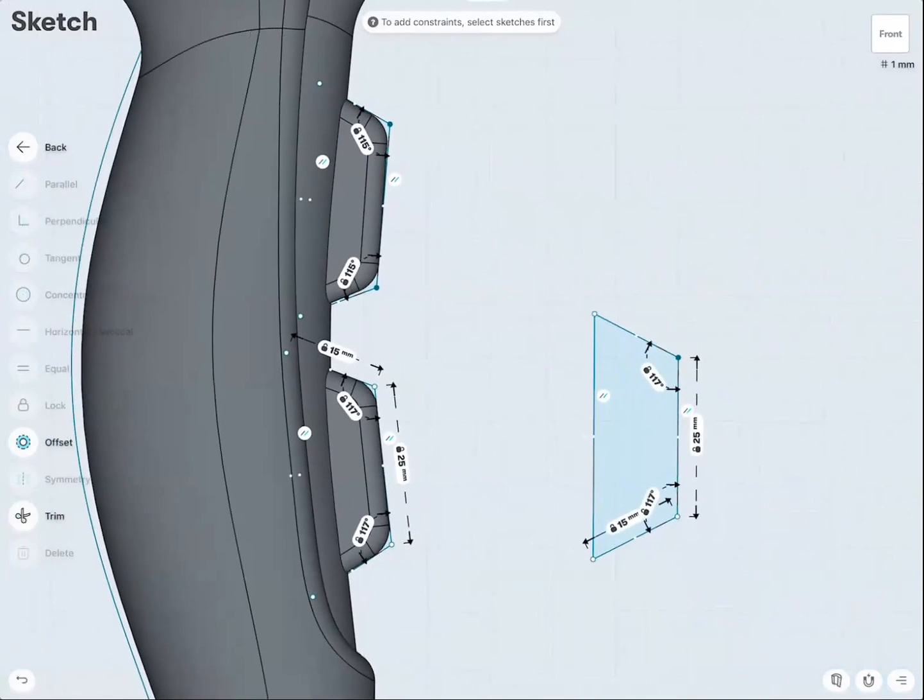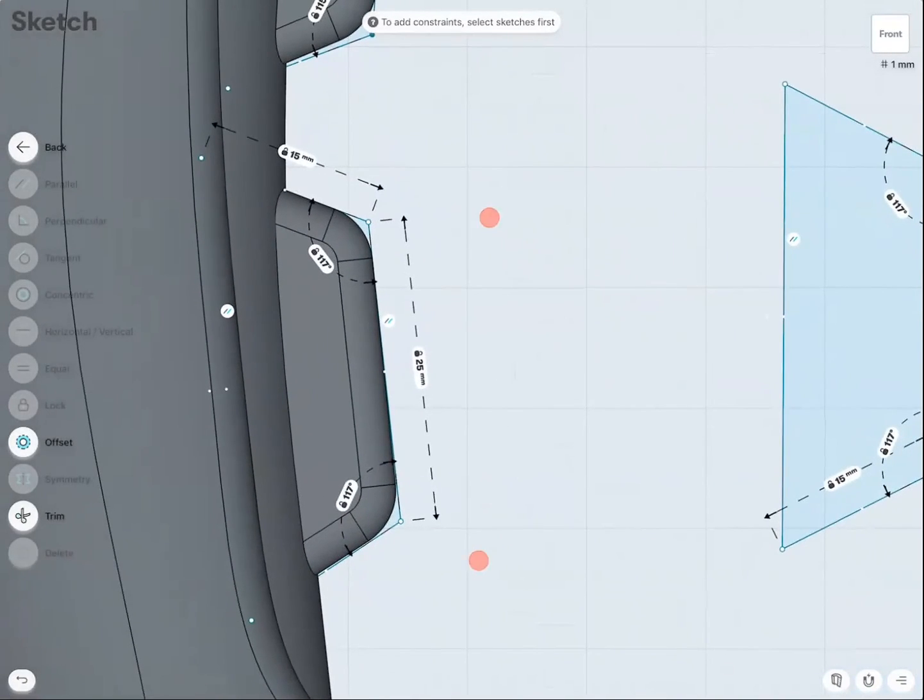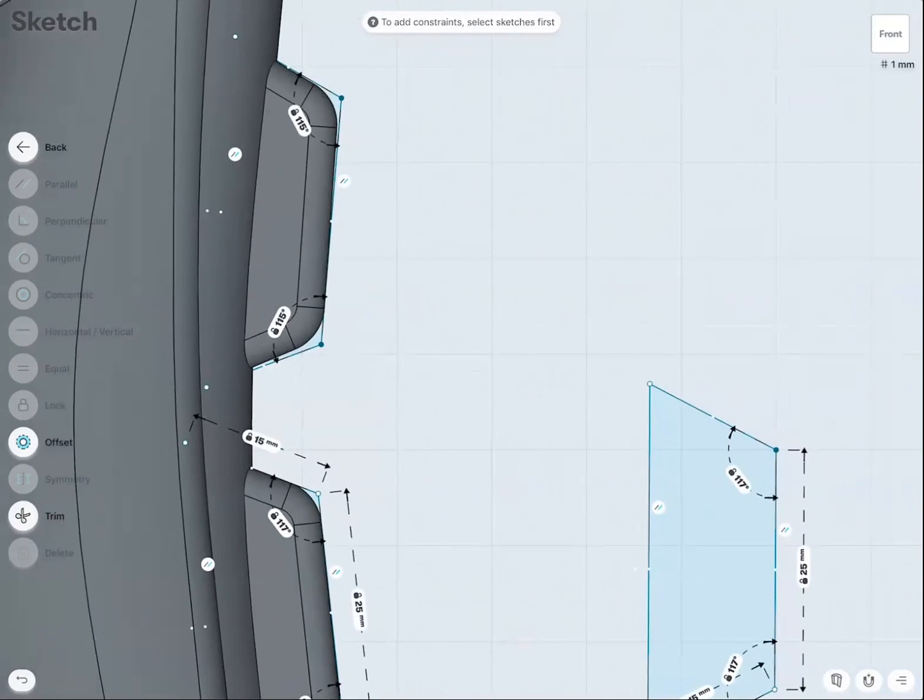And that pretty much was the way I rebuilt and found all the dimensions for the sketch here, with 115 and 117 degree inner angles for the corners, and 25 millimeters as the length of the button. So by simply starting to draw a sketch and rotating it, always having some constraints already in place, the 115 degree angles for the corners, and locking one point, I can then always rotate around the locked point.